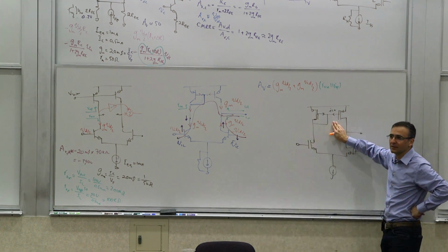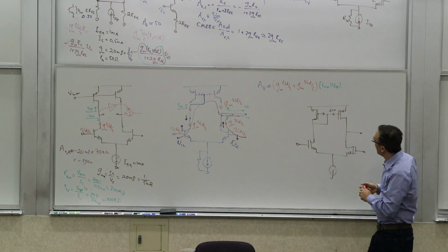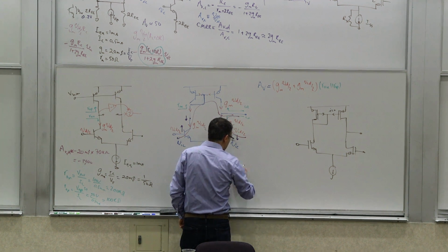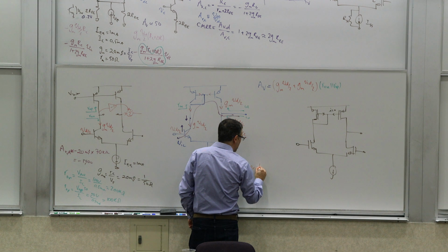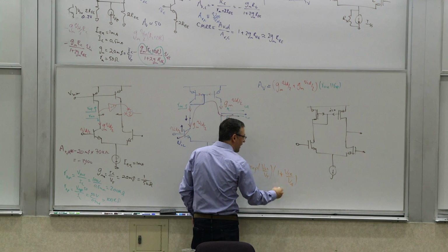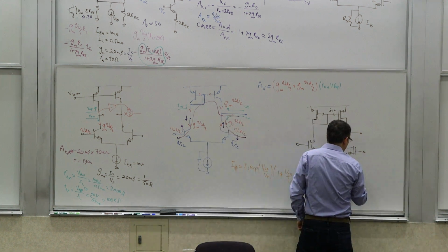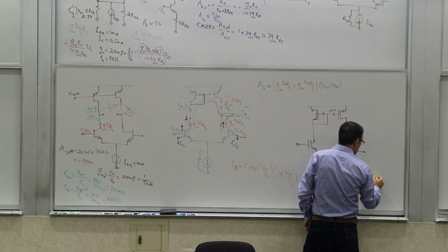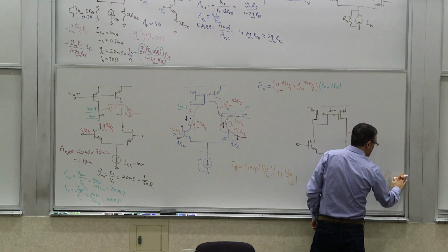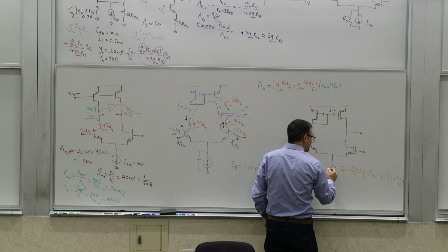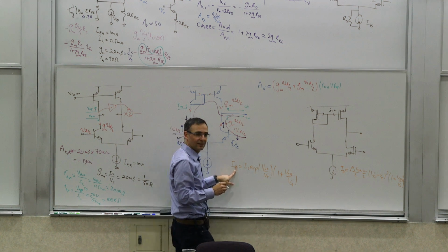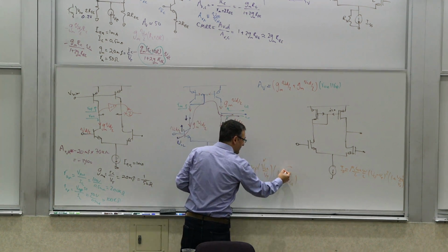Let's say in this case, in the MOSFET, right? Because what determines this voltage is really this. In the case of a bipolar, we had IC is IS e to the VBE over VT times 1 plus VCE over VA. And in the classic MOSFET, we had mu n Cox over 2, W over L, VGS minus VT squared, times 1 plus VDS over VA, or lambda, not squared. So that was ID. So they share the same VBE, and they share the same current. If current is the same and VBE is the same, then the VCEs have to be the same.